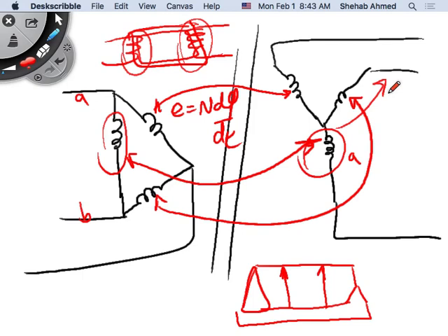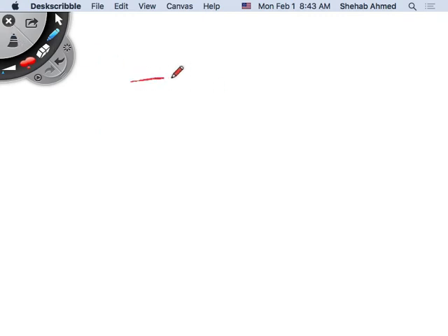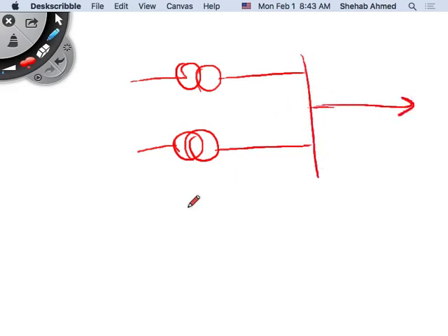Because if you're doing protection engineering, if you're designing the protection of a power system, you cannot have phase differences between, for example, let's say you have to feed a load with 2 different transformers. This is how you resemble the transformers. You feed a load with 2 different transformers. And let's say this is a delta star, this is also a delta star, right? But these are 3 separate windings, and you're connecting them yourself physically, right? So you cannot just connect them any way. You cannot just take one terminal here, connect these 3 terminals together, and then put the other 3 anywhere I want.